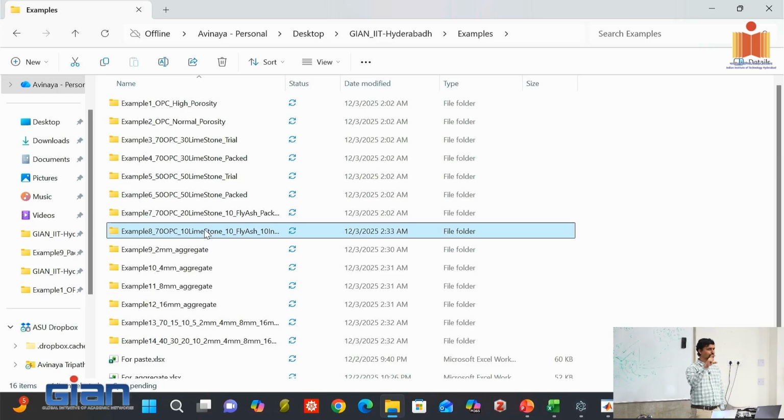If you remember, I showed you at a point it just has a force selection and it starts giving you porosity value, solid fraction, amount, number of cement particles, number of anhydrous, number of limestone, number of inert materials, and all those in a list. So you check those values and you put it to a porosity such that you have the porosity to accommodate that water.